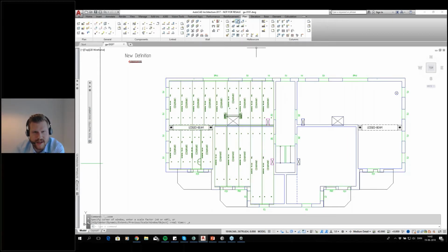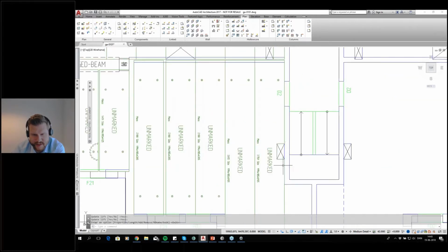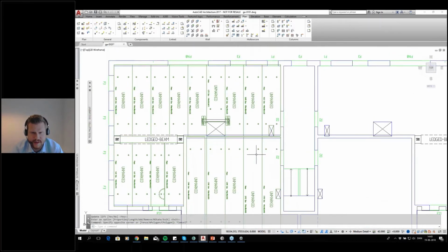So what I can do there then is go in, press Edit Slab, choose slabs that I want to do something with, which in this case are these two. And I say I want to add and update the lifters in each of the elements. And now you can see these are no longer magenta or purple. And if I hover over the element here, we can see that it's actually cut out. This box we see here is, of course, part of the external reference we still had.